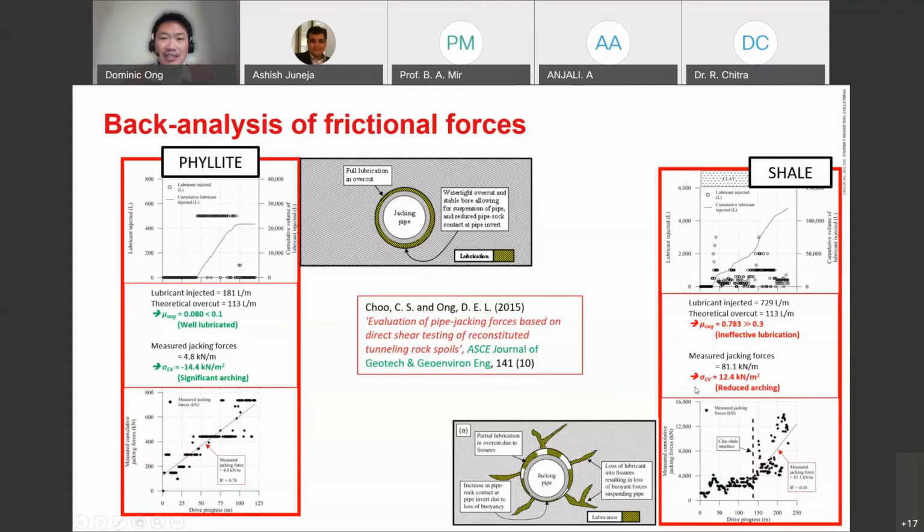So what phyllite is telling us is that even though we have RQD 0, as a rock mass under confining pressure the fissures do not open up. They provide a kind of watertight situation where your lubricant does not get lost. The time you have an issue is when you sink a borehole and try to extract the sample, and you get out 0. So we already roughly know this is happening, and this is how we prove it. It gives us another idea: let's do in situ testing next time to characterize rock strength instead of sinking boreholes to extract it. That was the recommendation for the next phase of the project.